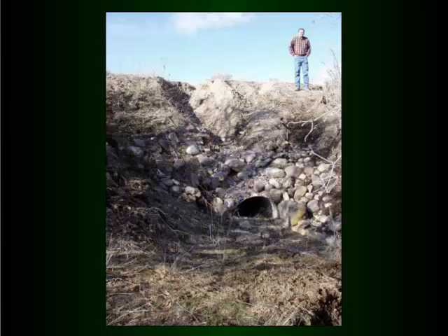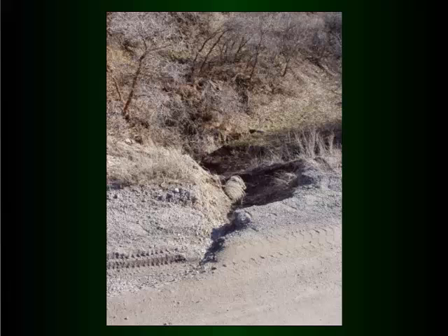Another pipe, looking at the road, water's coming down the edge of the road and then coming off right into your drainage, and you can see that it's cutting, and all this material is depositing downhill, down below, and filling up the pipe. And this is the same pipe looking at the road. You can see this coming off the road surface, coming right down in and basically filling up the pipe. And this is a rock road, so there's also an investment in the rock that's actually being lost down into that gully, as well as filling the pipe up. And like the pipe that had the concrete head wall on, that's not an easy pipe to replace, so obviously it would be good in that situation to divert that ditch water somewhere so it doesn't fill it up.